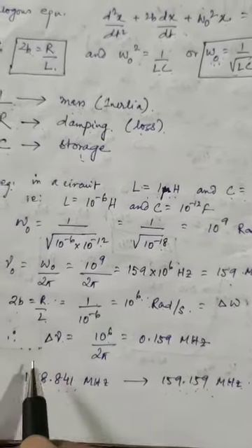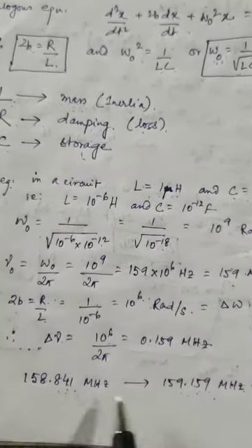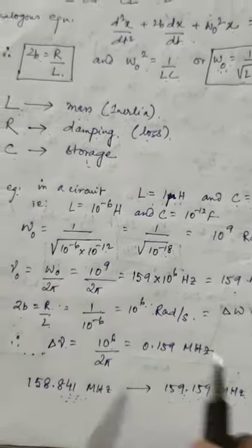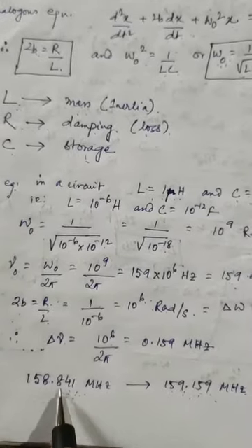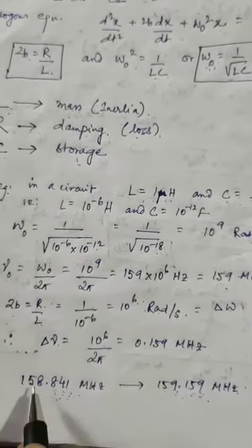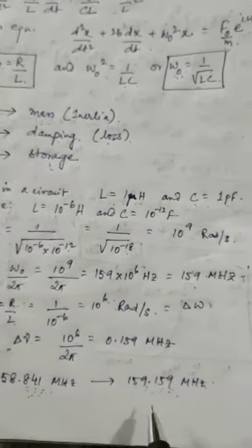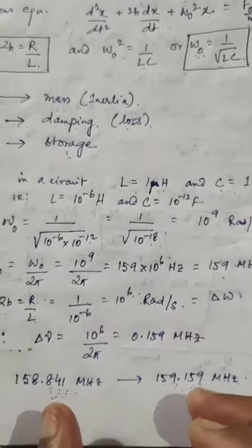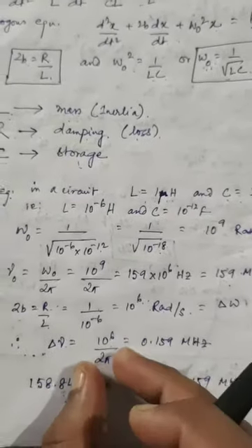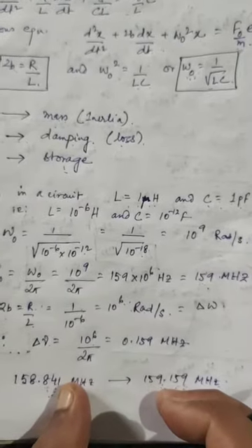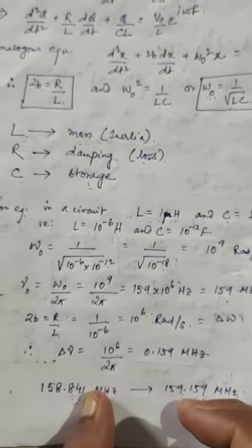You remember that it is at these frequencies where the power goes down by 70%. We did it in the previous videos. So if you go below this, the power is still lower, and if you go above this, the power is still lower. So we can approximately say that within this range of frequencies, that is the bandwidth, the power delivered to the system is maximum.